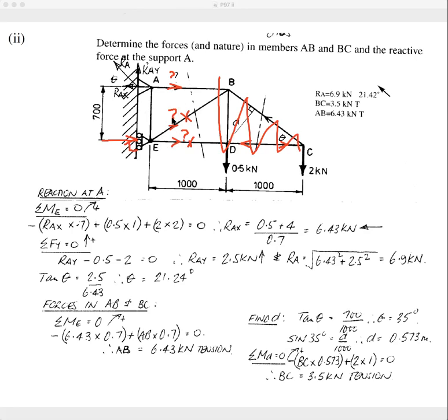Now, if you were to take moments about this point out here, regarding this cut truss that's shown here, the sum of the moments about that point has to equal 0 because this cut section is still in equilibrium. But you don't have to take moments about a point there.